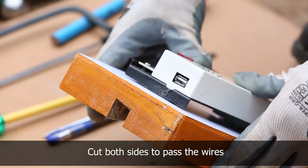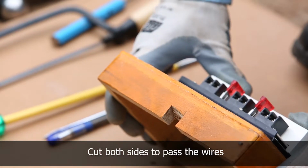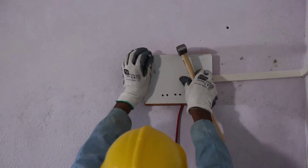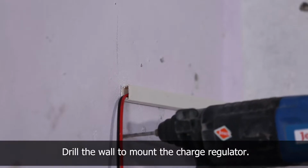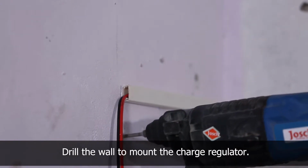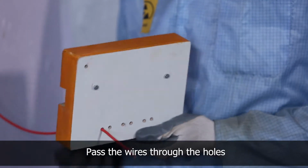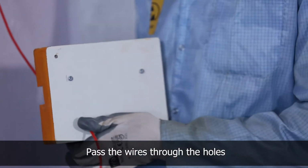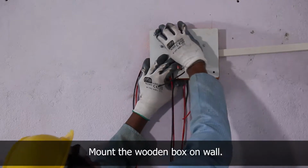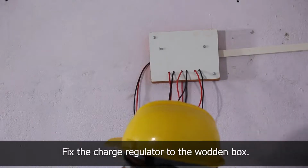Cut the wooden box on the side so that the wire and PVC pipe can be passed through. Pass the wires from the panel, battery and load through the drill holes of the wooden box. Mount the wooden box on the wall and fix the charge regulator to the wooden box.